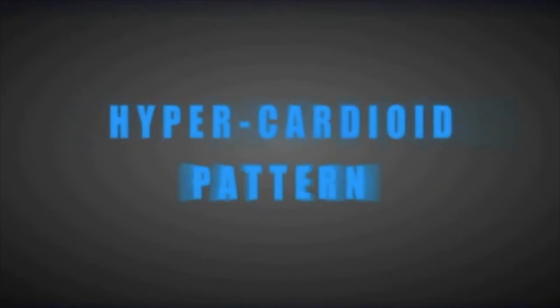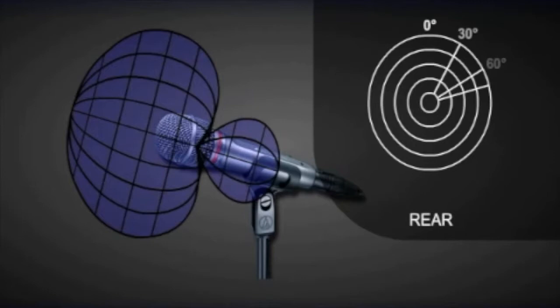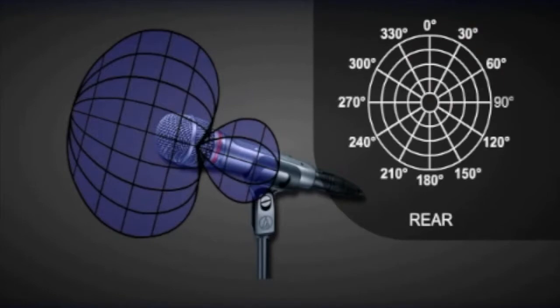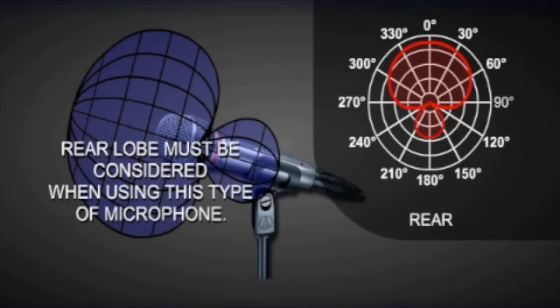A hypercardioid pattern is more directional than a cardioid and supercardioid by further reducing the side pickup. The drawback of the hypercardioid pattern is that it has an inherent lobe to the rear, which is not highly sensitive, but must be considered when using this type of microphone.